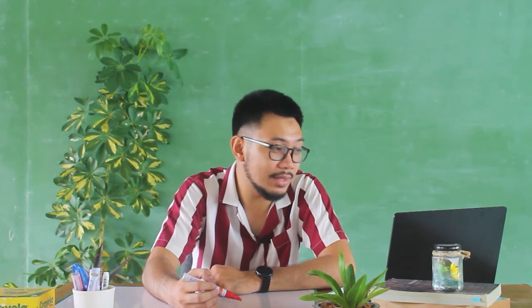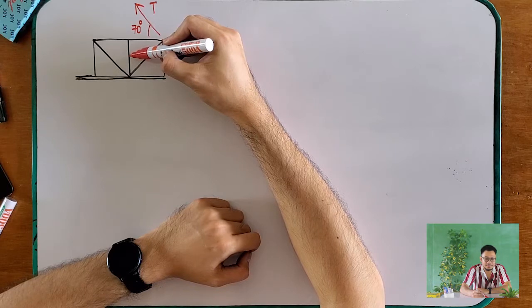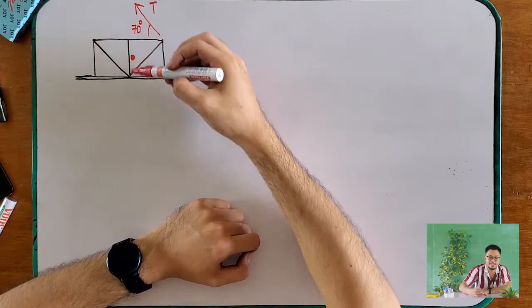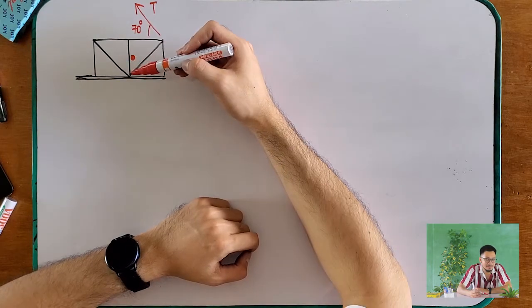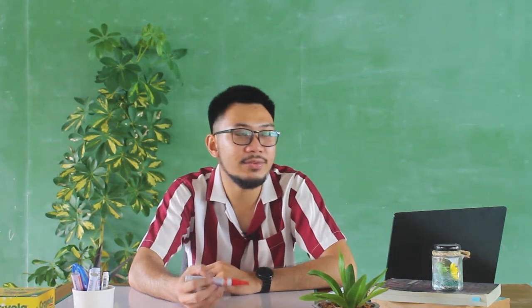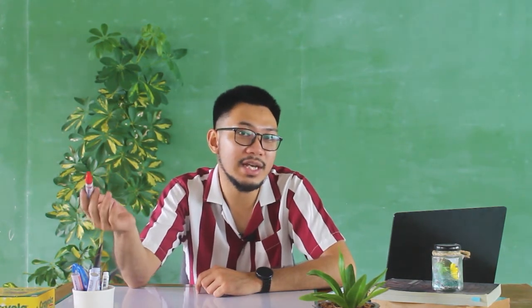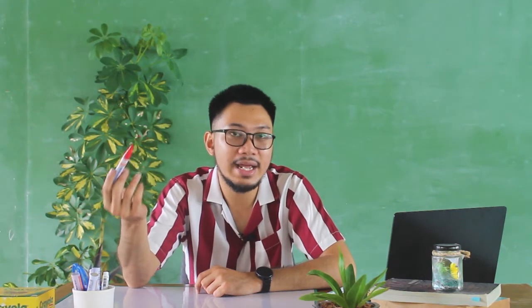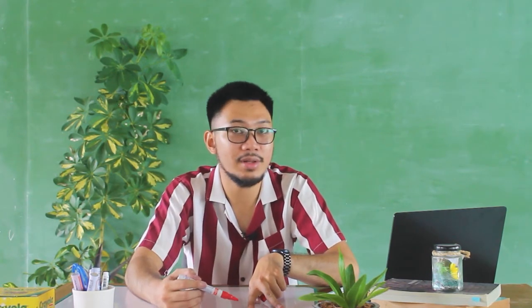And it says here that our platform has a mass of 200 kilograms. And then it is assumed that the 200 kilograms is located on its center of gravity. Usually our assumption, if you are given the mass or the weight of an object, is to apply that weight at the center of gravity of that object or that structural member.